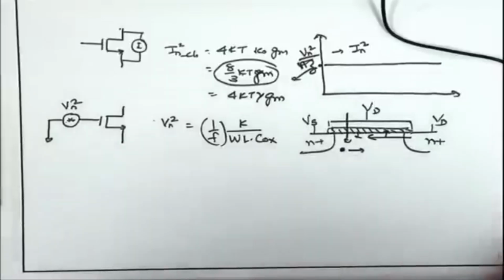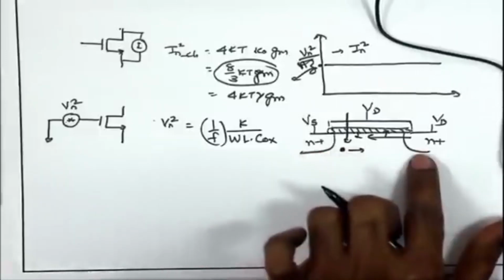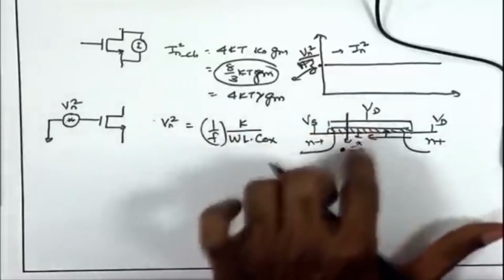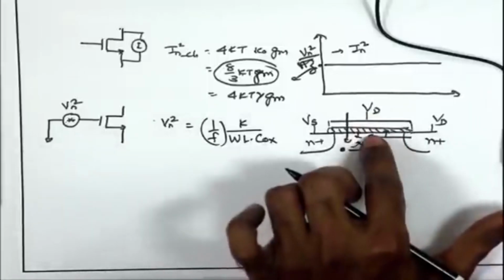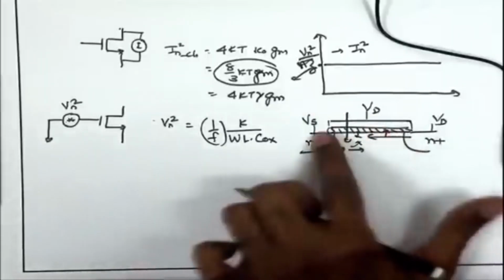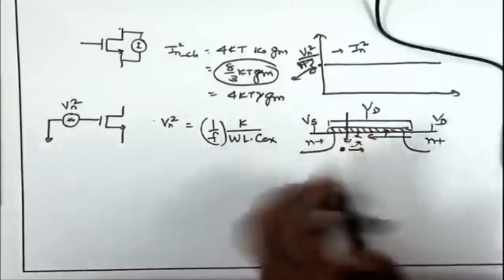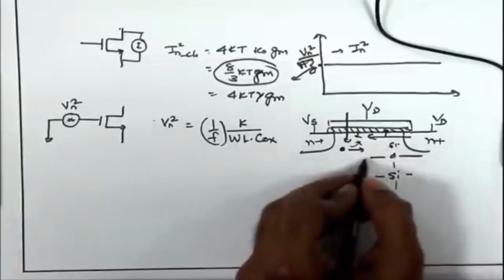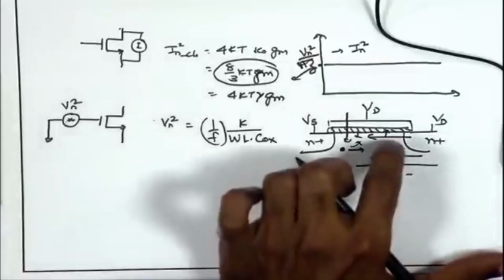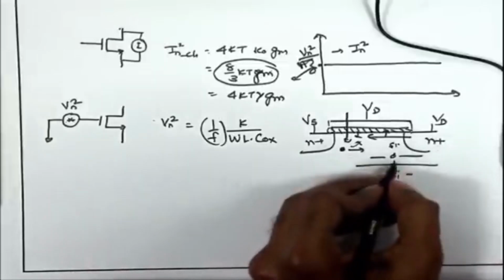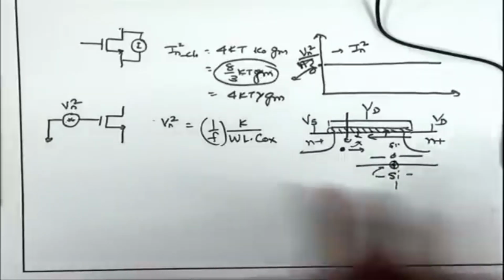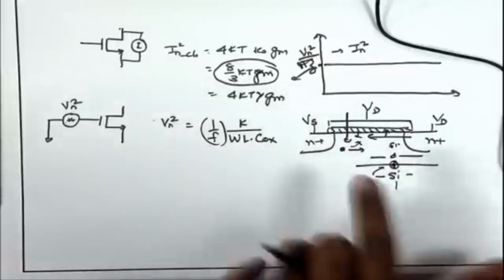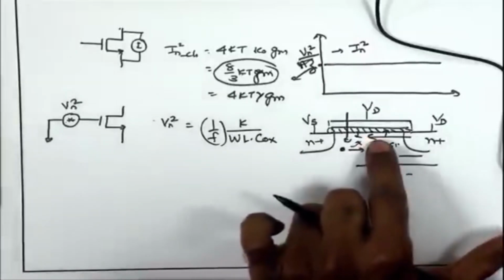So, electrons definitely have a strong positive velocity from source to drain because of the positive electric field. Likewise, they do have some gradient of motion or velocity in the direction perpendicular to the gate, and there is a continuous trapping detrapping phenomenon that can happen at the interface. So, the interface is not perfect, you can have some dangling bond at the interface between the Si and the SiO2. Between the SiO2 and Si, you can have certain bonds which are broken, they lead to dangling bonds, and this becomes the trap of these electrons which are accelerated in the channel. So, there is continuous trapping detrapping of these carriers at this interface, because of which we are having an effective change in the threshold voltage.